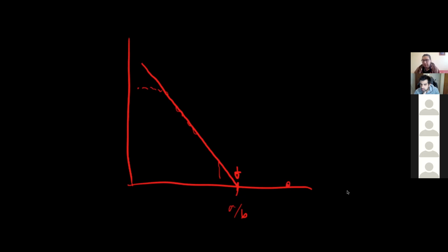What I think is the best thing you can do is a probabilistic analysis and calculate the probability of having an event above a specific magnitude. And that is based on your rock support design. When you design rock support, it is designed to contain a rock burst based on a seismic event of a specific magnitude.